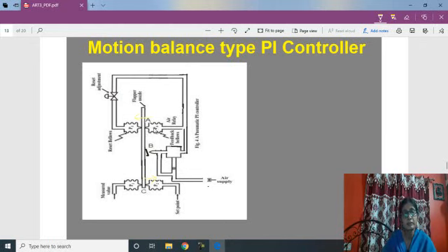So this causes the movement of a decrease of pressure signal, and the pressure signal at this bellows element will also decrease. And after a certain time delay, through the restrictor, the pressure of this bellows element will rise above this. So in the next level, this point A will move towards right again.